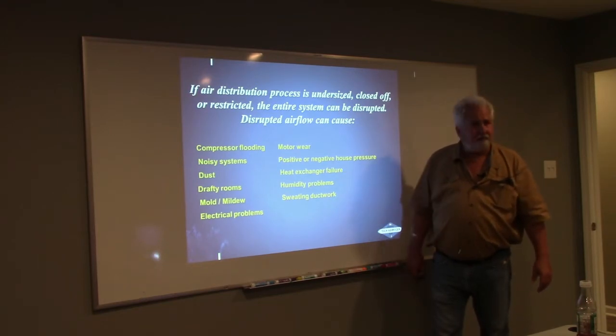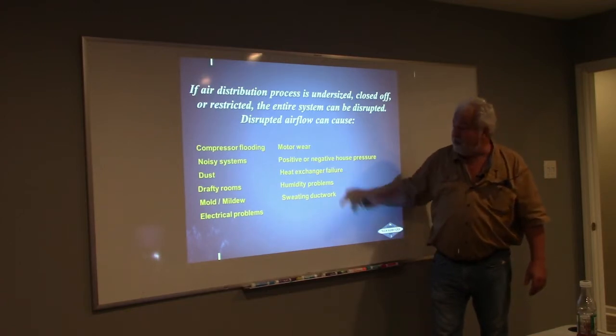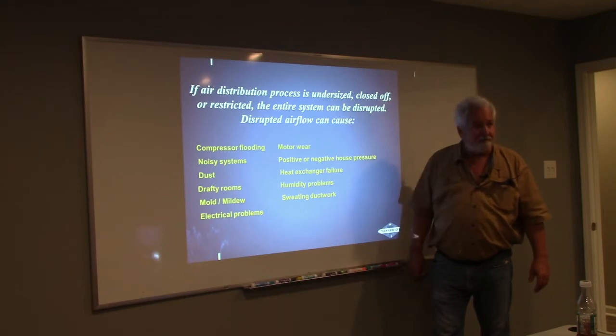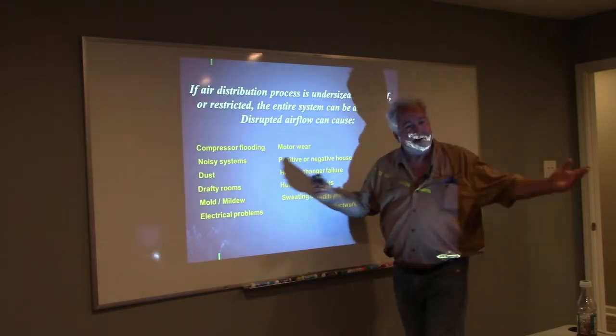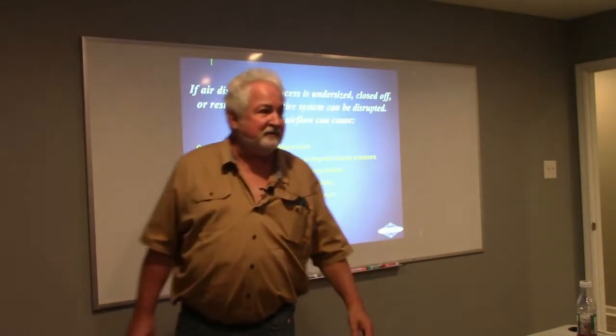Heat exchanger failure? Yep. Because it's not moving the air across it, that heat exchanger is going to get hot. Right. Good. Humidity problems? Absolutely. Sweating ductwork? Yes, absolutely. That's all of the things we're going to talk about, and you've seen it.